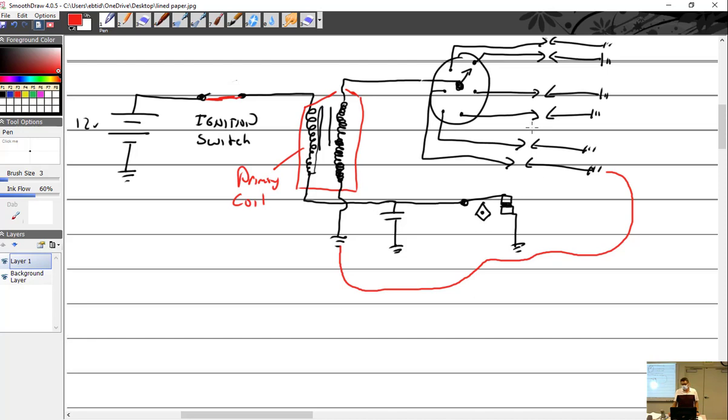Now, how much voltage is built up in the secondary? A lot. About 20,000 volts. It's going to be 20 or more or less. Now, the funny thing is, how much voltage is built up depends on how much of a gap it has to jump. If it's a very, very tiny gap, it will only build up enough voltage to jump that gap and flow. Because it's an easy jump, so it builds up to that, flows, finds ground, it's done.